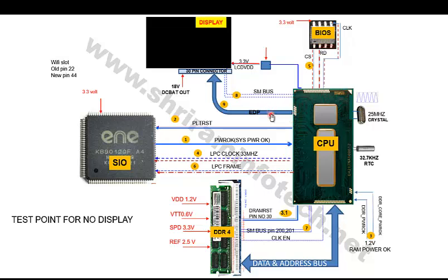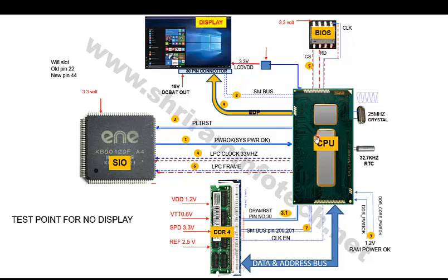This port is basically called an EDP. EDP means enhanced display port. Enhanced display port is an advanced display port other than the LVDS. It generates the graphic signal to the LCD like this and generates the display. So friends, in this way the display appears on the screen.